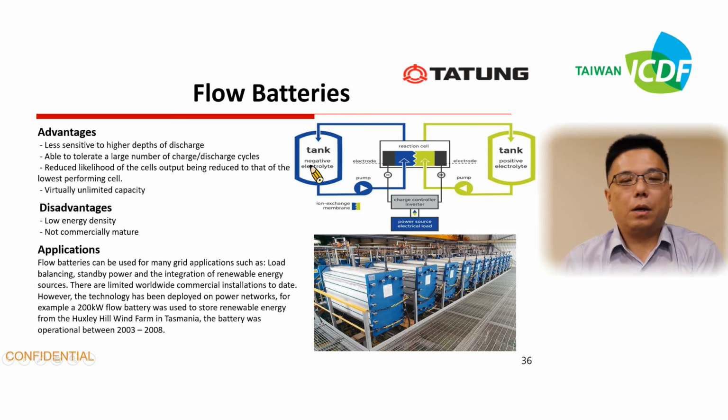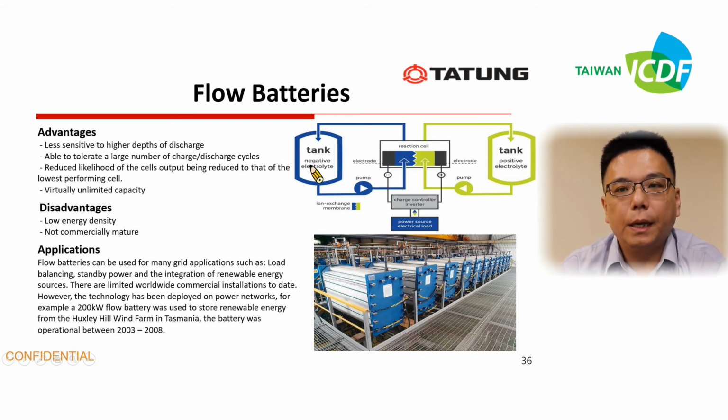So compared with other batteries, it does not have a fire issue, so it can tolerate a large number of charge discharge cycles and reduce the leakage of the cell output caused by low performance cells. But it has other disadvantages: a low energy density and it is not yet commercially mature.